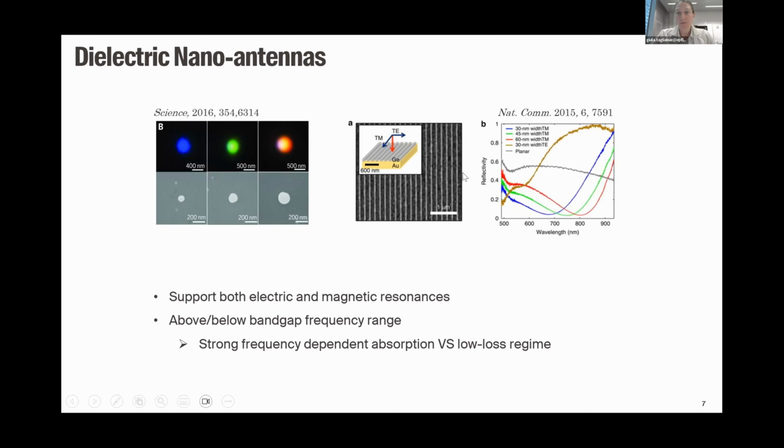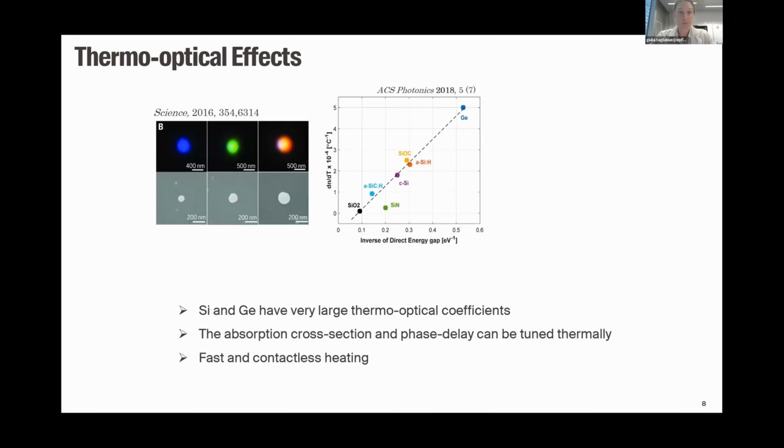So you see here, for example, using the strong light absorption in the semiconductor, one of the early demonstrations from the group of Mark Brongersma, where they made this ultra small, ultra thin germanium photodetector based on resonant germanium nanobeams. And again, normally if we only think of the optical application, we want high quality factor resonances, but absorption can also be engineered and be quite useful.